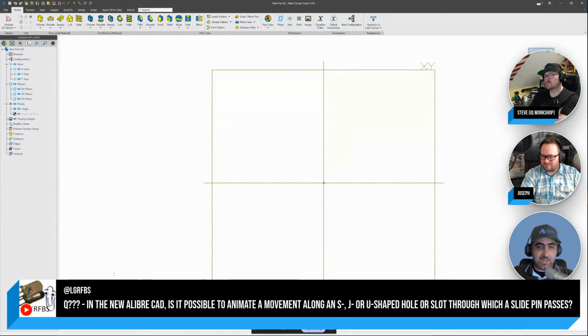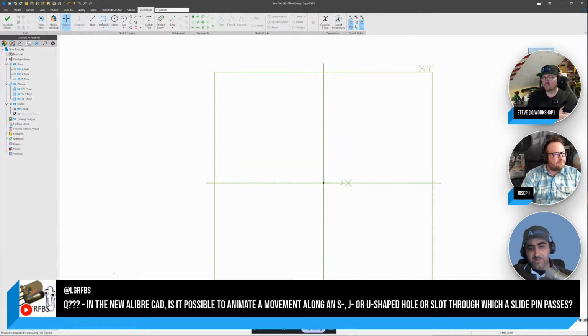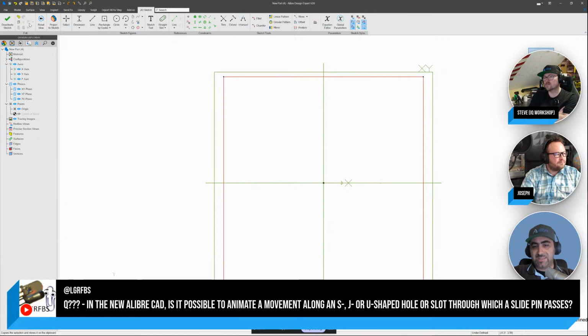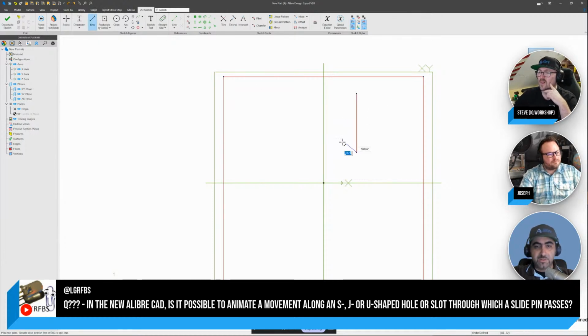That's a feature that Alibre already has, exporting a PNG. So what it does is it just drives the assembly for a small step, grabs a PNG, a little more, grabs a PNG, and then makes a GIF out of it. But that is the closest to actually animating an assembly you can get in Alibre. You'll find that add-on in the forums. It's really, really cool and interesting.